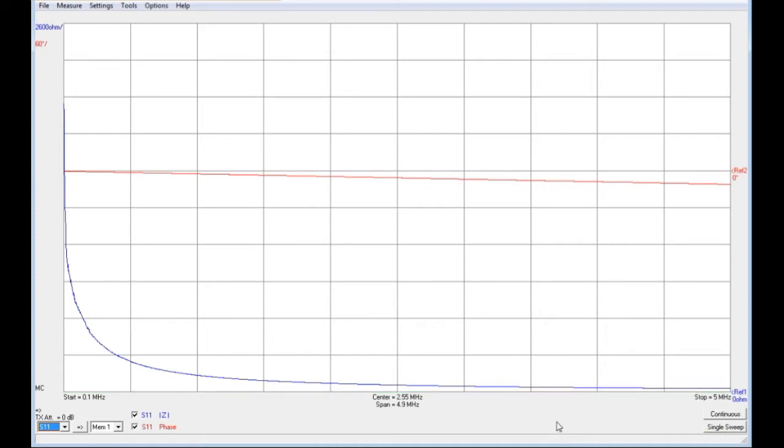Okay, now one thing I did forget to mention in the previous video, when we were setting up the connection and looking at cabling and how to work with the Tesla coil, I did not mention that one has to be very careful about how one connects this device in relation to whether you've got your generator connected. The inputs to this VNA are 0 dBm maximum, that's 1 milliwatt, and no DC. So 0 DC, 1 milliwatt RF are the maximum inputs, unattenuated inputs that both the TX out and the RX in.